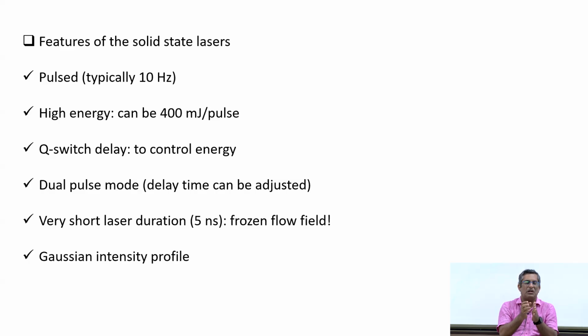We also should be able to control the time delay between the two laser pulses. Then, as I said, it should have high energy if the seeding particle size is very small, so we should be able to control the energy. This can be done. We should also be able to control the delay time, the time between the two pulses.